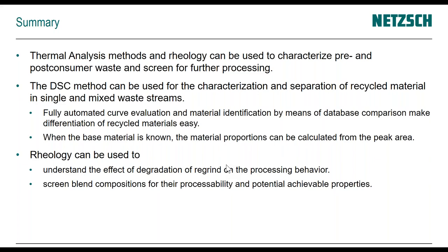By having fully automated curve evaluation, as we have AutoEval with our DSCs, and material identification and a database system, it's really easy to differentiate within your recycled materials. Having an auto sampler, you can go through a lot of samples really fast.